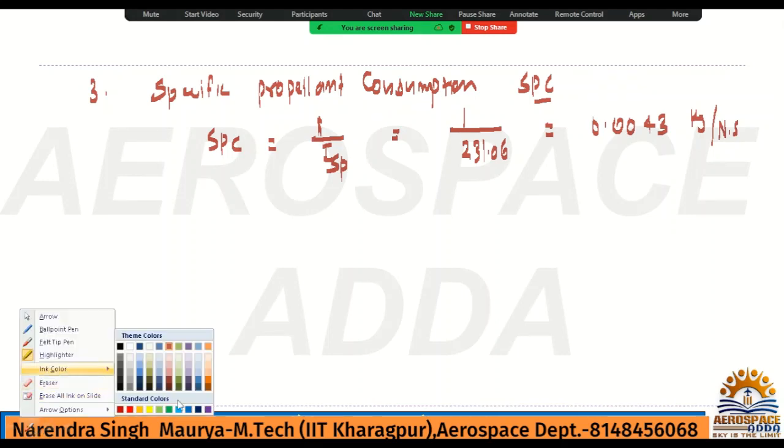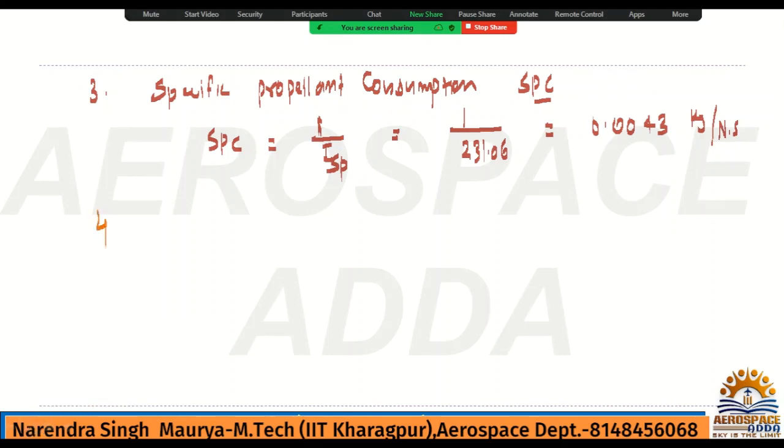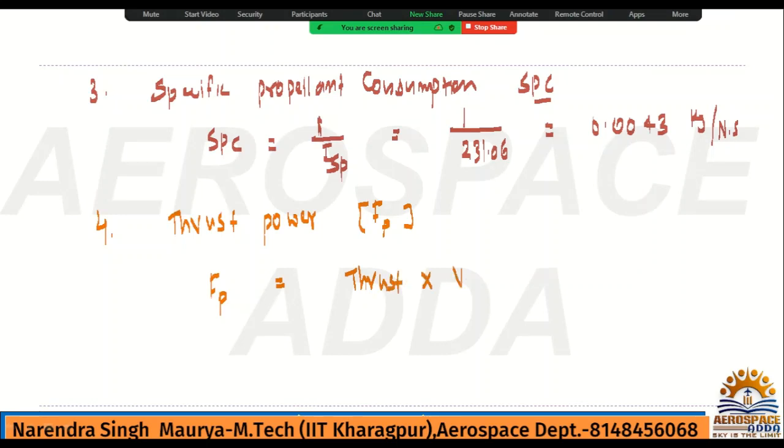Okay, we'll go for number 4. What is the number 4? Thrust power. What is the thrust power? Power is force into velocity. What is the force? Thrust. What is the thrust you have here? 17 kilonewton, so 17 into 10 power 3.